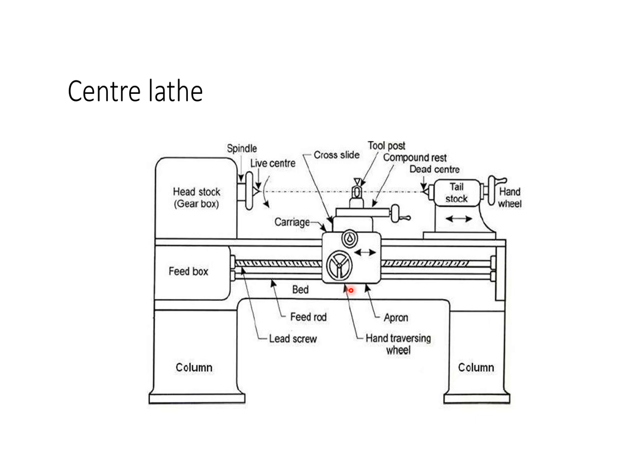Next, the compound rest. The compound rest is mounted on cross slide, carries a circular base called swivel plate, which is used during taper turning to set the tool for angular cuts. The upper part known as compound slide can be moved by means of hand wheel. Then the tool post. So it is fitted over the compound rest. The tool is clamped in it.